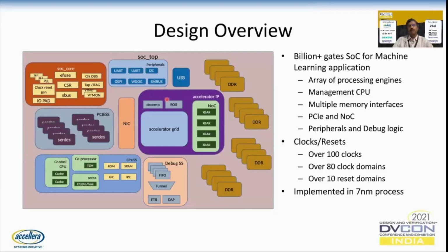The complexity of the clock domain crossing analysis stems from the network on chip interconnect, which is essentially a large number of distributed async FIFO. This is a flop-based memory with granular clock gating. Third-party IP bridges with asynchronous clock domain interfaces also increase the complexity. Design itself being large, doing at the SoC level, the CDC analysis was time consuming.